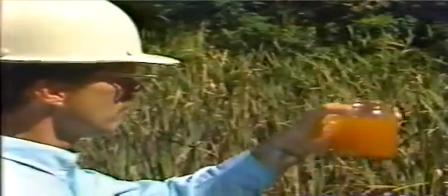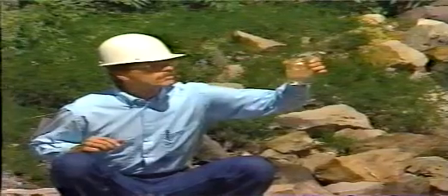Now let's turn our attention to problems that may be found in the downstream area. These include increasing or cloudy seepage, sand boils and sinkholes, unexplained increases or decreases in controlled seepage from toe drains or relief wells, and problems with the devices that measure seepage flow. Seepage downstream from the toe becomes a serious problem when erosion of foundation materials or piping occurs. Cloudy seepage indicates piping, so check the clarity of the seepage. Sand boils result from excessive seepage pressure.